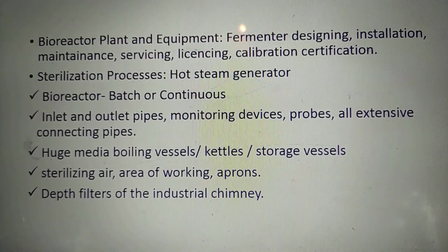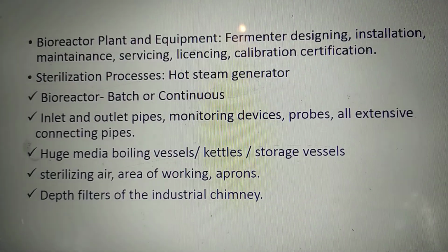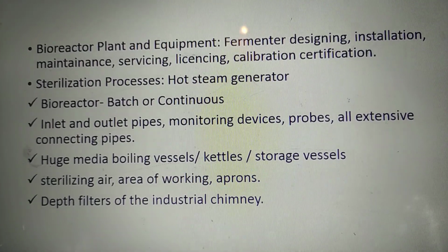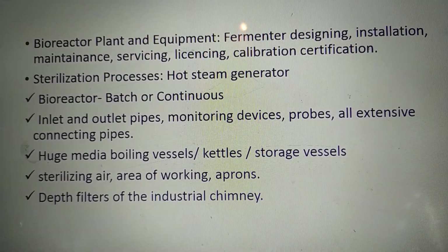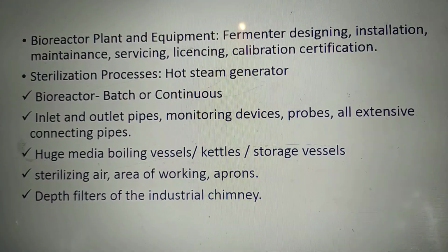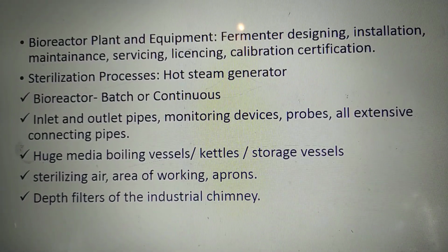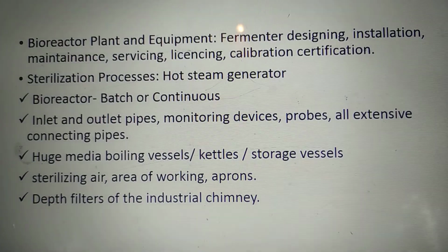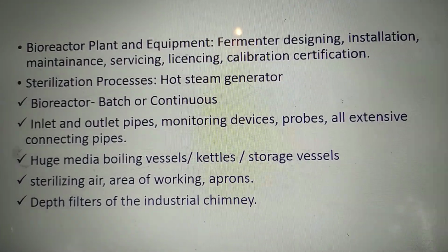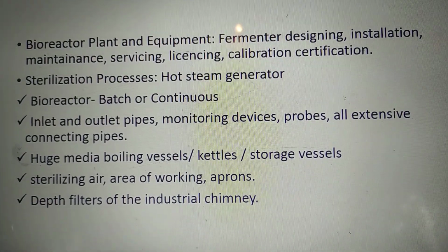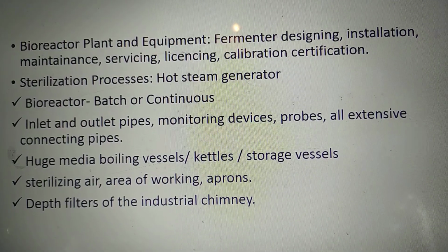Sterilization process means every little thing of the industry. The bioreactor, the inlet pipes, the outlet pipes, the probes, okay? Then the environment, the air, working area, the people who are working should wear sterilized aprons, etc. And the huge media preparation vessels, storage vessels, depth filters.